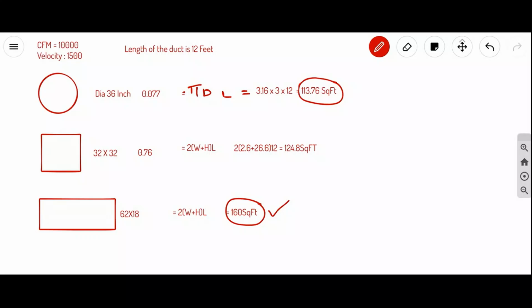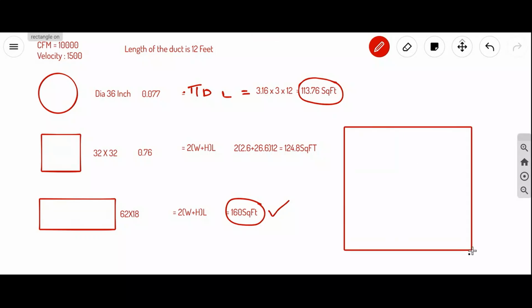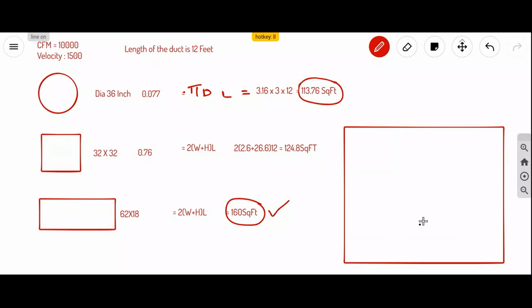No. But still, why are people using rectangular ducts? Wherever you go, you mostly see rectangular ducts, right? Because the grills we get are more rectangular. Above the false ceiling we will have only some sort of place, a restricted space, the clearance. This is the plenum space, right?